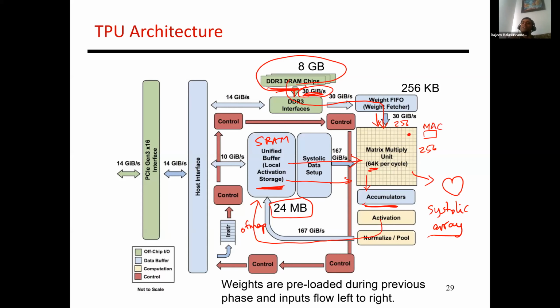I can go into a little bit more basics shortly, but essentially you're bringing in the weights from off-chip memory. That's expensive. That's why you want to maximize reuse of weights as much as possible. That's why we did things like batching. If you're doing convolutions, there is natural weight reuse, right? Every time you bring in a weight, it gets stored in all of these things over here. So let's take an example of a kernel, 3 by 3 by 64. To compute this first neuron of my output feature map, I need to do 576 multiply accumulate operations.